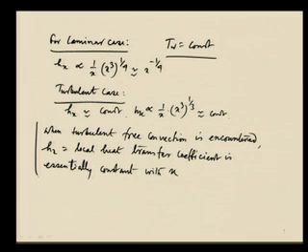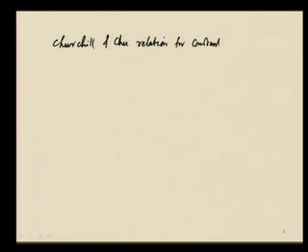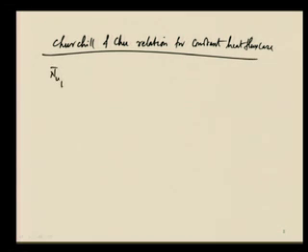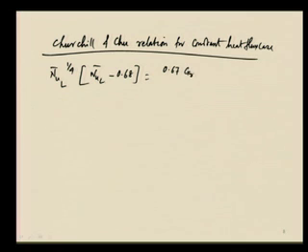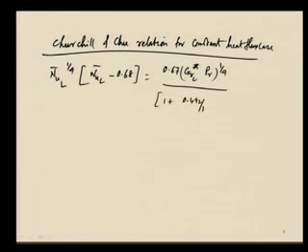Now, in the case of constant heat flux, Churchill and Chu have given a slightly complicated correlation. They say that Nusselt average based on length to the power 1 by 4, now Nusselt average minus 0.68, is equal to 0.67 into the modified Grashof number Grashof L star into Prandtl, whole to the power 1 by 4, divided by 1 plus 0.492 by Prandtl whole to the power 9 by 16, whole to the power 4 by 9.